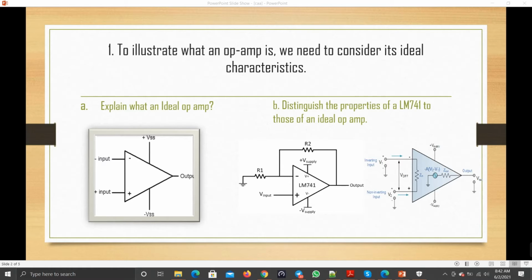In an integrator circuit, the DC gain should be limited by adding a feedback resistor in parallel with the capacitor, else the output will saturate. For an ideal op-amp, there is infinite gain, zero input current, zero offset voltage, and zero phase shift. It also has infinite frequency response and no transient issue. Practical op-amps do not have any of those.